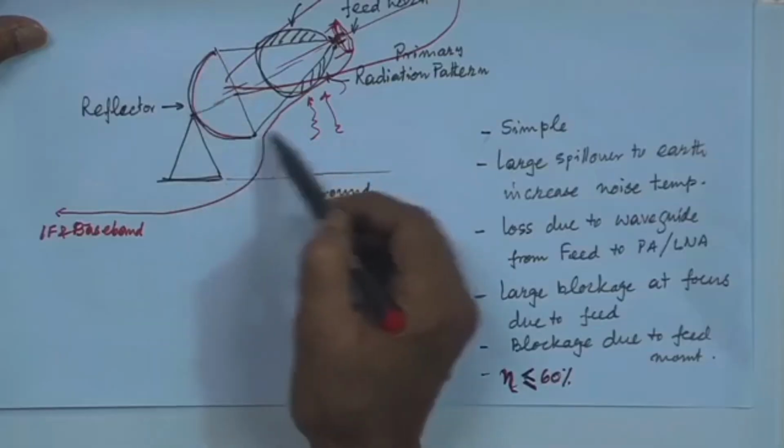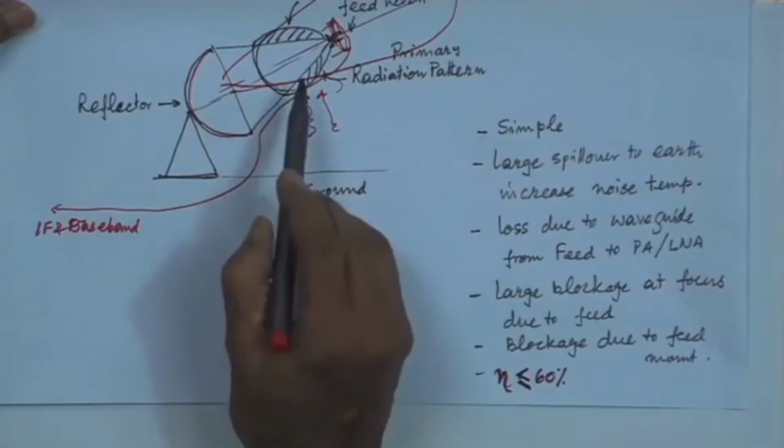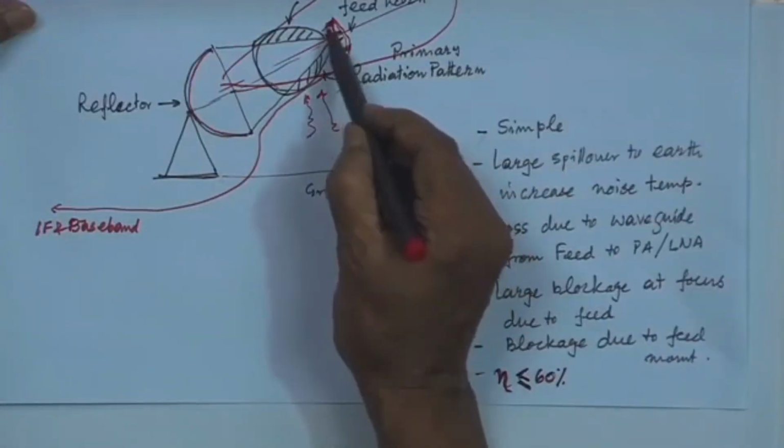You have seen the cable operator head end, from the building or from the rooftop, where the cable operators receive the satellite signal and then transmit through the cable, our TV cable operator. So, there you will see a lot of these prime focus, simple type antennas which are looking at different satellites, and then they are picking up the TV signals which are broadcast by those satellites and then multiplexing and sending through the cable. So, this is one of the common places where you can see this, but then we have this blockage coming into the picture.